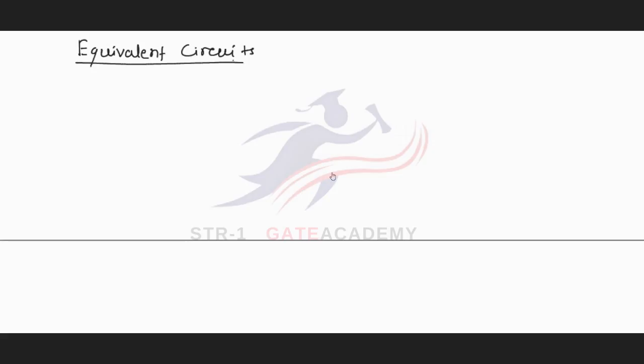Equivalent circuits will be based on the biasing of the diode. If the diode is forward biased, it will be replaced by different components in the circuit. Forward biased means its anode terminal is at a higher potential with respect to the cathode terminal. According to the definition, a diode conducts only in the forward bias case. So, seeing this diode as ideal, I expect it to operate like a short circuit.